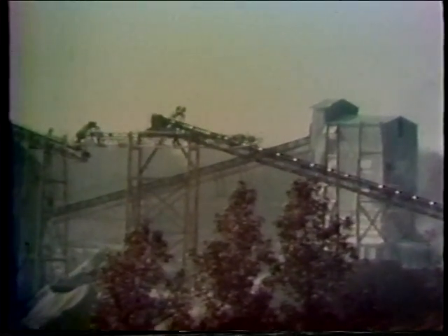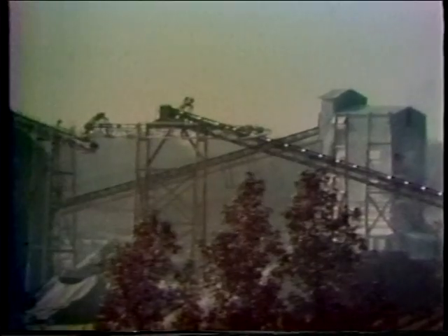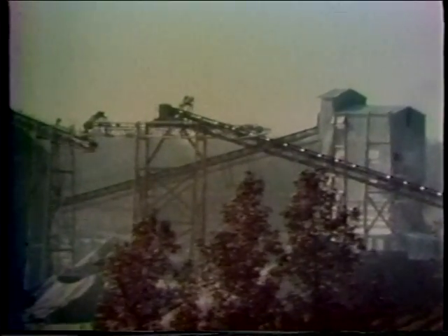Finally, there must be a frame or superstructure to support the idlers, the pulleys, and the drives. This frame is normally composed of welded, fabricated structural steel. There are several different configurations a belt conveyor may take. They may be flat or inclined up or down. Now, with conveyors inclined, in order to keep the material from rolling back down, it's sometimes necessary to have either a rough top belt or even slats, which may be bolted or molded onto the belt.